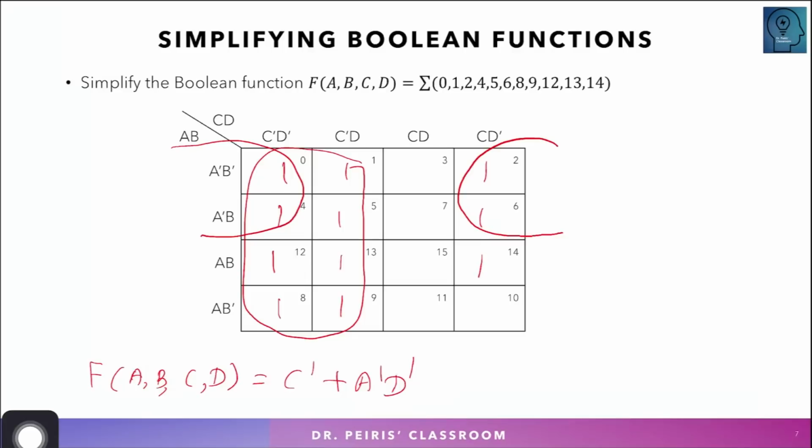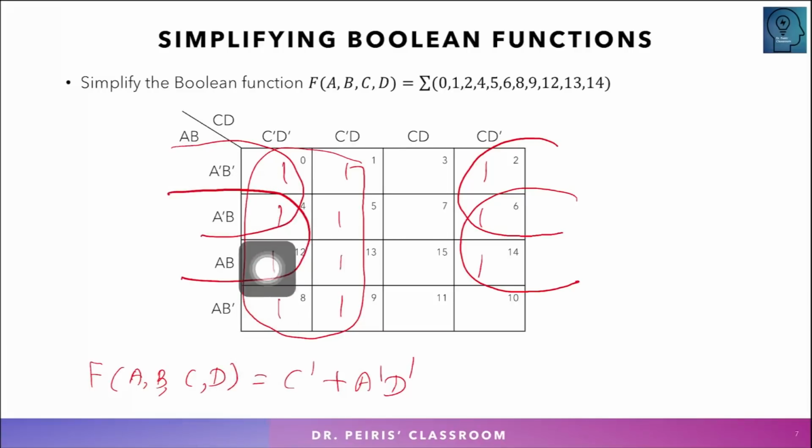So you finish that. Now how do we do this one? You can do 14 and 12, but that's not the best way to do it. The best way is like this: 6 and 14, and then 4 and 12. So 6 and 14 and 4 and 12 makes a single group. Here it is in these 2 rows.